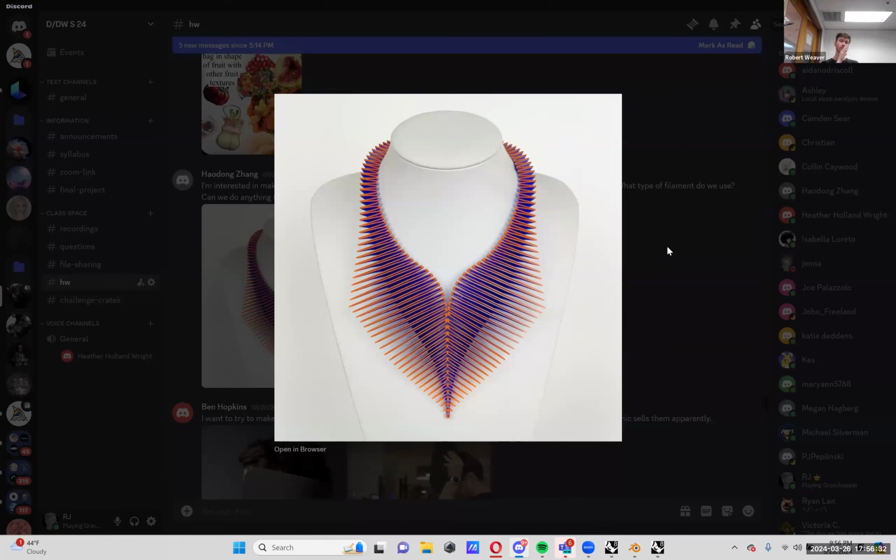Yeah, I mean, so you could do PLA or that clear stuff as long as the wall is super thin. Like you could do this corrugated shape, and then if it's only one wall of thickness, then it would expand like an accordion. Okay. So you could experiment with that. We've had people in the past in the lab do something like that. Maybe it would be like just design the surface and offset to both directions.